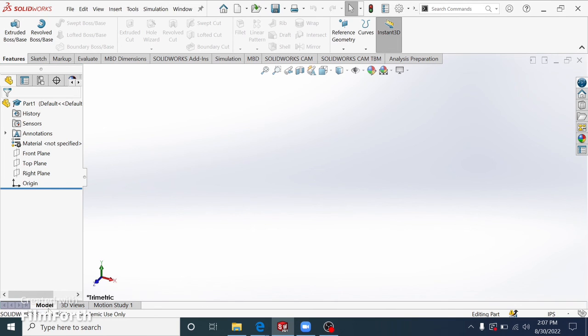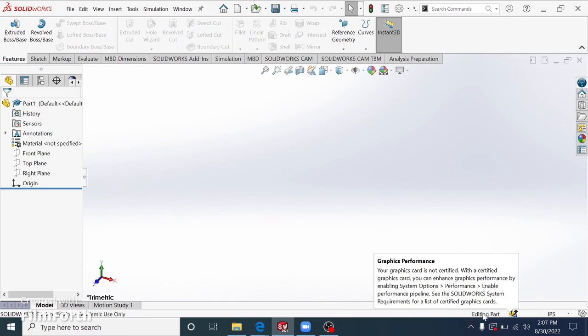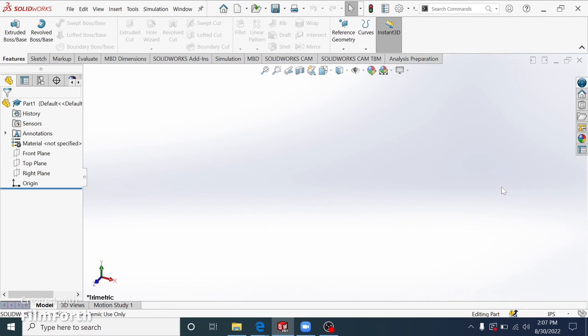We're not going to worry about these ones right here, that's until later on in the future for other videos. But down here you have these other functions. You have the edit part, graphics, performance. This is the main one that's going to be important because this will have an error, and that's because of the amount of work building up in SolidWorks. You'll have an error on the notifications side that says you have to make room, or you have to look into your memory space of how much is being rendered in SolidWorks. So that's going to be a big error.